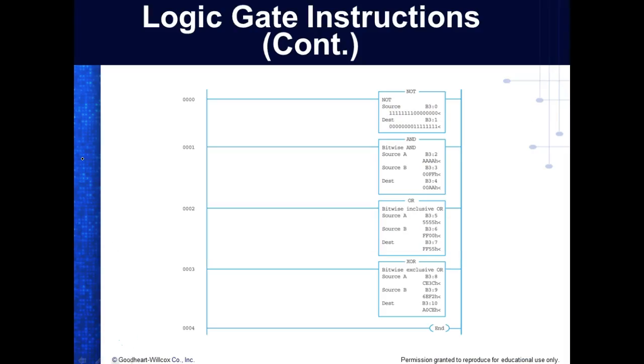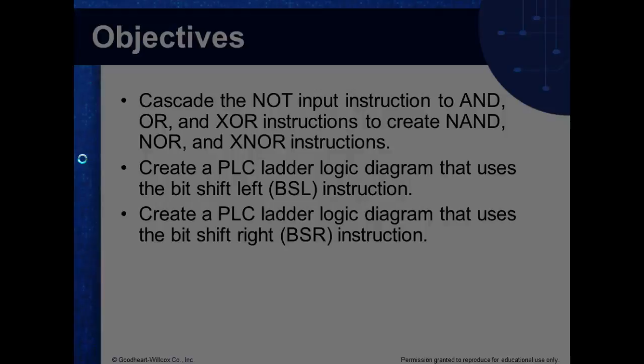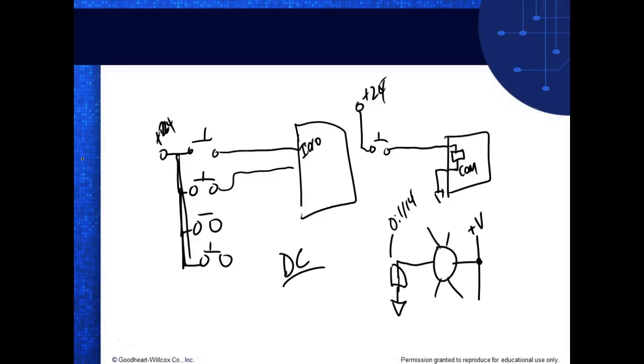This is the one I have open. Of course, I erased all that. If they are sourcing, if I press the button, I get a 1. If they are syncing, I press the button, I get a 0. Okay, y'all understand that? So what am I getting back? I'm getting a 0 when the switch is closed. So that means these inputs are hooked up. These are syncing devices. So my port is going to be, I have to look it up for sourcing, right? Y'all understand it?